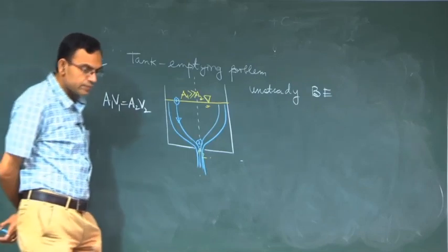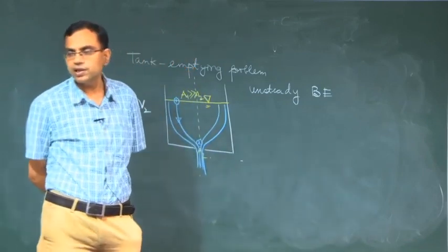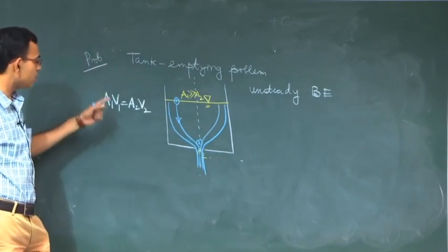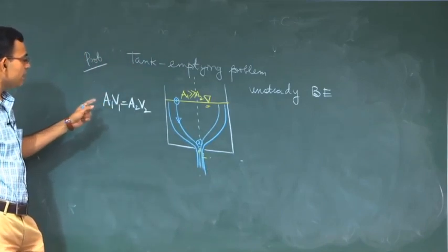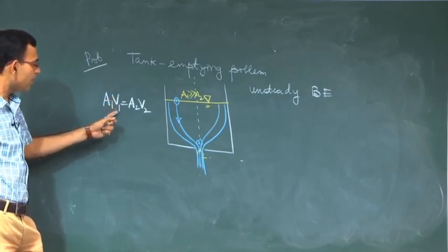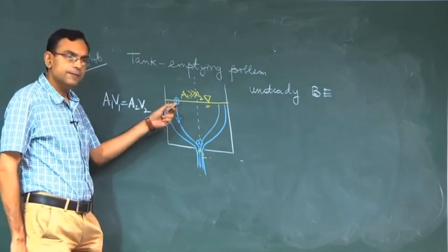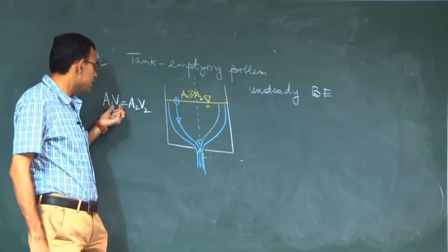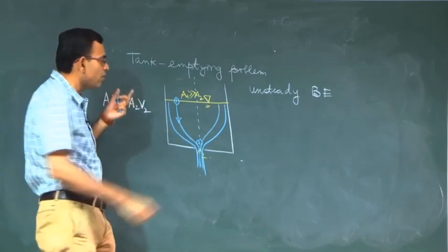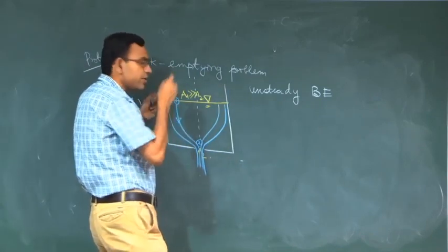We have earlier discussed that this equation is also a very elusive equation, because when we write this, not only is rho constant, but we are also assuming that V1 is the velocity at point 1 here. Fundamentally, this equation is A1 into V1 average equals A2 into V2 average. That means A1 into the average velocity over section 1, not the velocity at point 1.